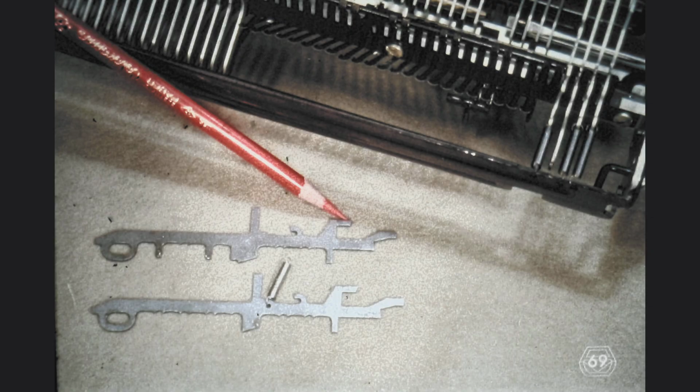American machines do not even have a selector bail for it. This seems to indicate that the underscore interposer does not filter out any latches when it moves toward the front. It turns out that the underscore hyphen interposer allows all the selector latches, which control the rotation of the element, to remain at their rest position. And as a result, all positive selector latches are pulled down during the cycle. Whenever the cycle clutch is made to operate without prior depression of an interposer, the machine will go through exactly the same process as far as the rotation of the element is concerned.